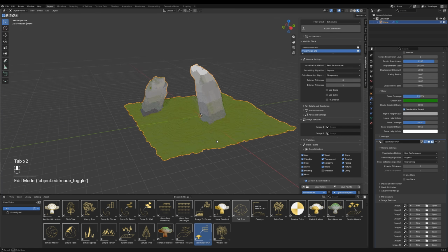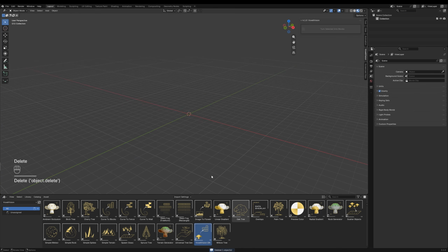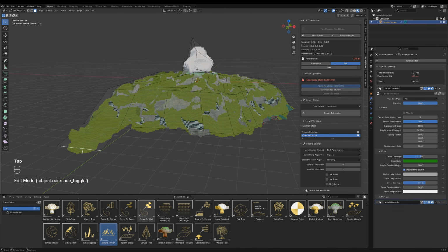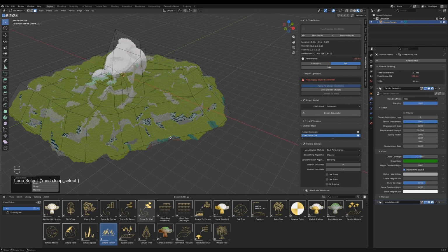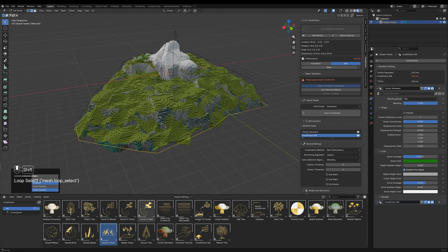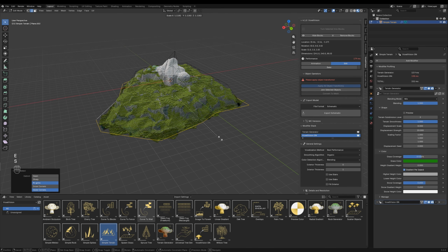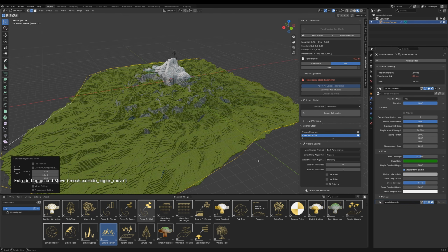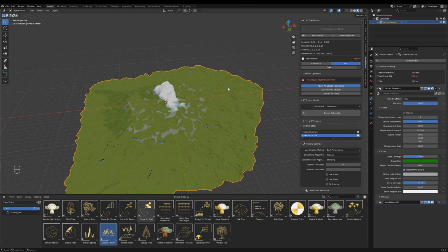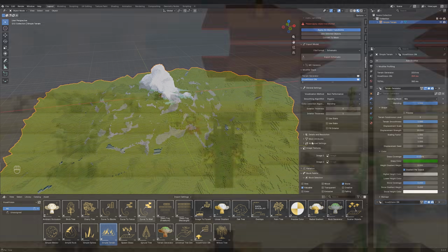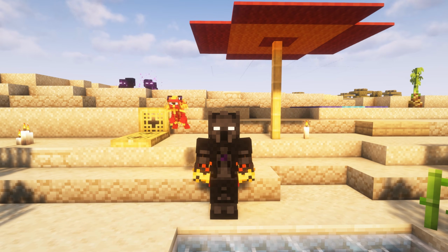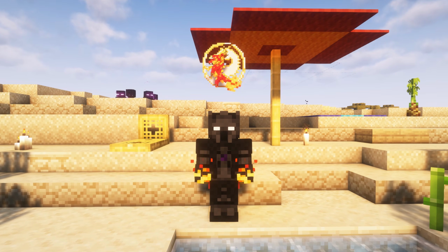This is the ideal version that you could perform. If we remove this again and drag in the simple terrain, you can see this is built off from smaller pieces as well. And then you can also select, if you go into edge select mode, you can hold Alt to select the edge loop, press E and S, and basically scale it to get a little plain, the grass plains biome with a mountain on top. And then you can go from here. So this is the modeling solution that you could use to create your own custom terrain.